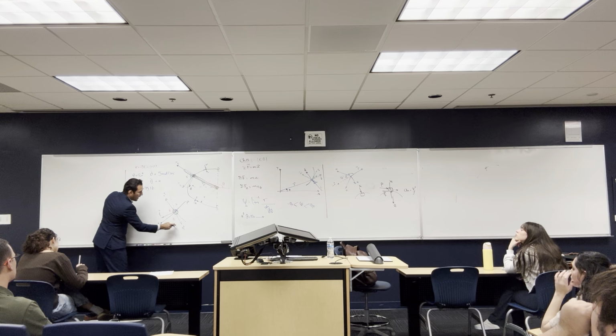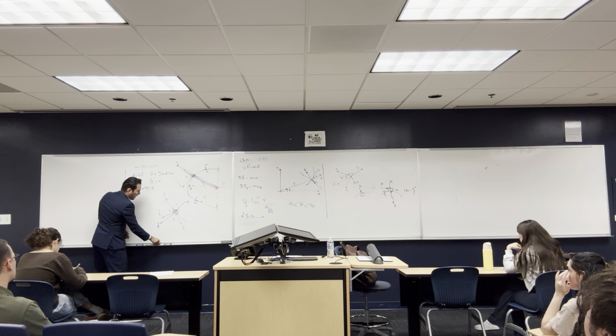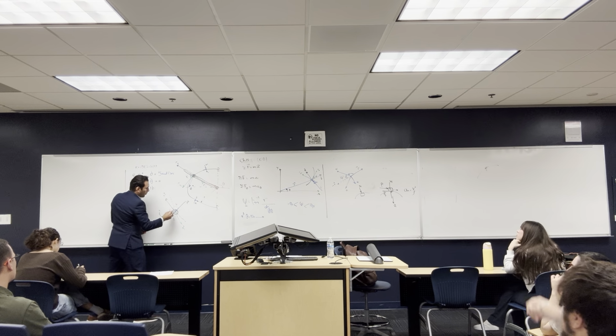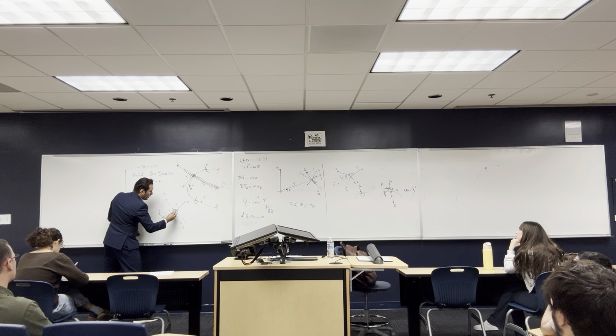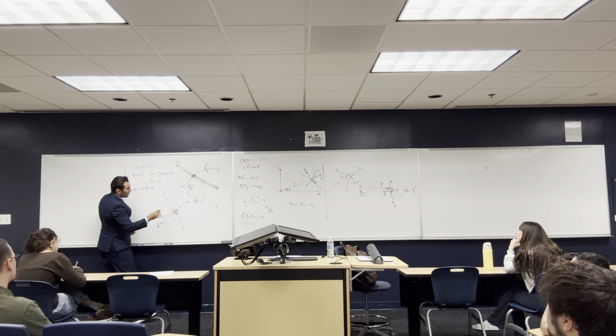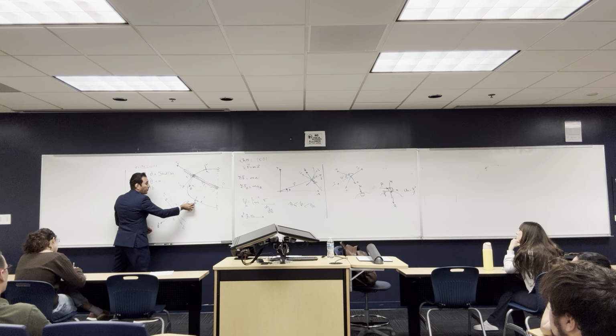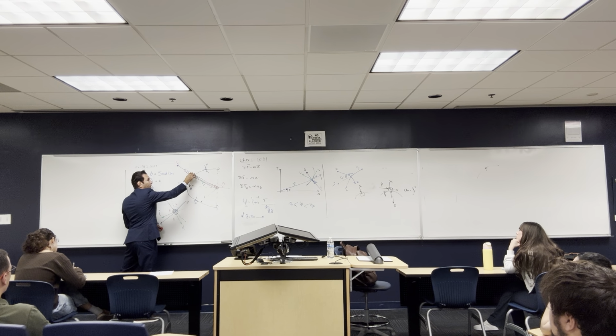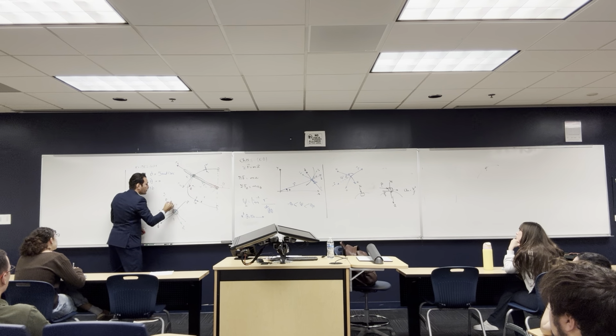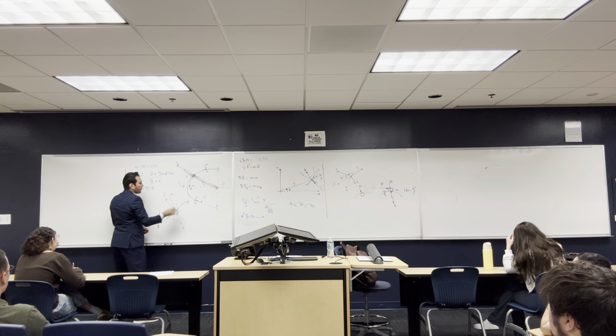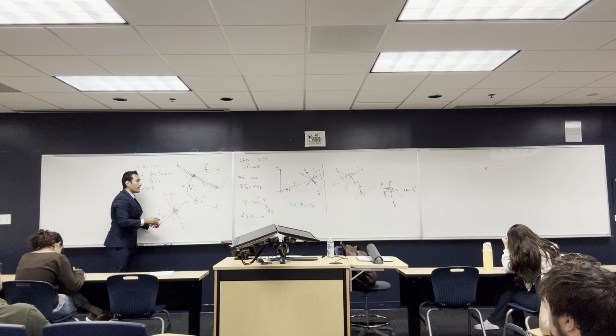So that is the n hat. So I'm gonna have the normal force in the n hat direction. Let me just focus. I'll find if it's positive or negative. So if this body is down, the n hat is gonna go that way, but my body's up at 120 degrees. So the normal force of this surface on this is going that way. So I have a normal force in the direction of the n hat, something like this. That's the only two forces that I have.